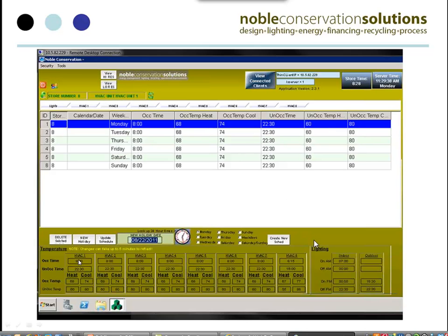We go down to the individual rooftop units, so the individual HVAC units, and can control each one of them separately as well, and that allows us to stage and control them uniquely based on how the building is set up. For example, if a building has the front of the building facing the sun, and there's a lot of windows in the front of the building, those different rooftop units that are serving the front of the building might have different settings than the ones that are serving the back. In addition to that, obviously, if the back of the building is northern facing and it's wintertime, and there's wind generally coming from that direction, changes can be made to those systems as well to make sure that the system is well balanced.